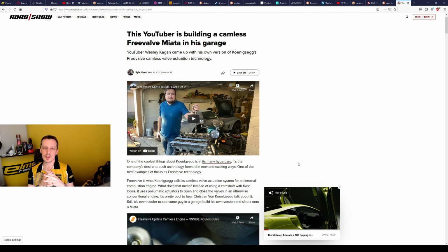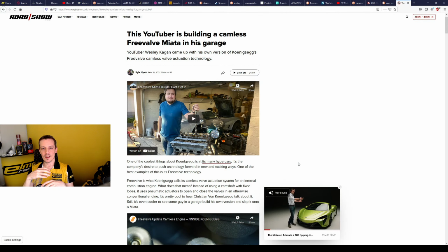No. So with F1 type, with the pneumatic valve springs, when you're talking about pneumatic valves, the valves are actually not pneumatic. They're traditional poppet valves, and you have a cam lobe that opens those. It's only the valve spring that is pneumatic. So you don't have a coil spring, but you have a pneumatic spring instead. So you have just air pressure that closes it, and you need to have seals on that, and pressure control valves and pressure adjustment stuff with the F1 type things.